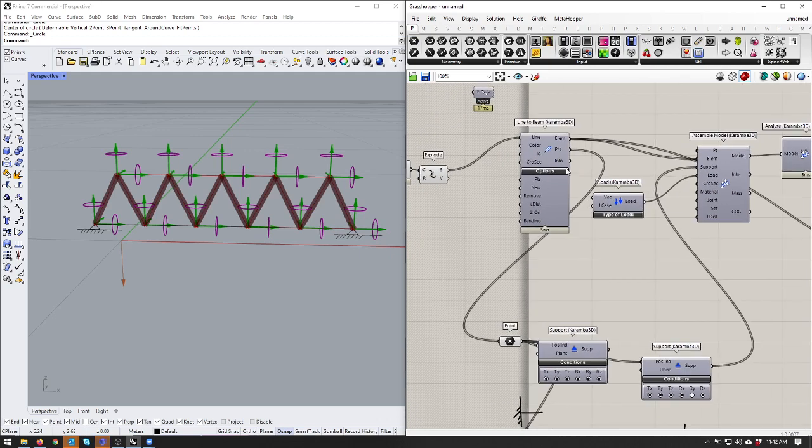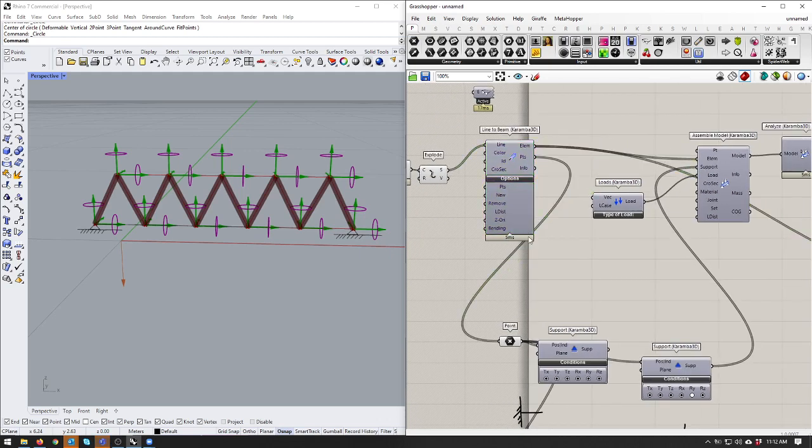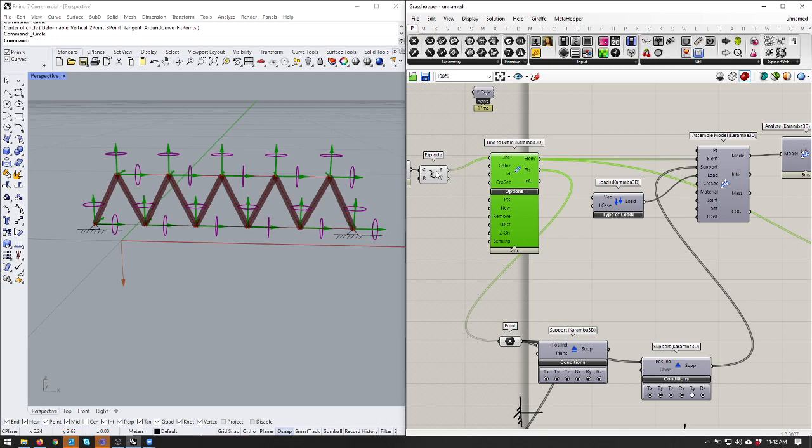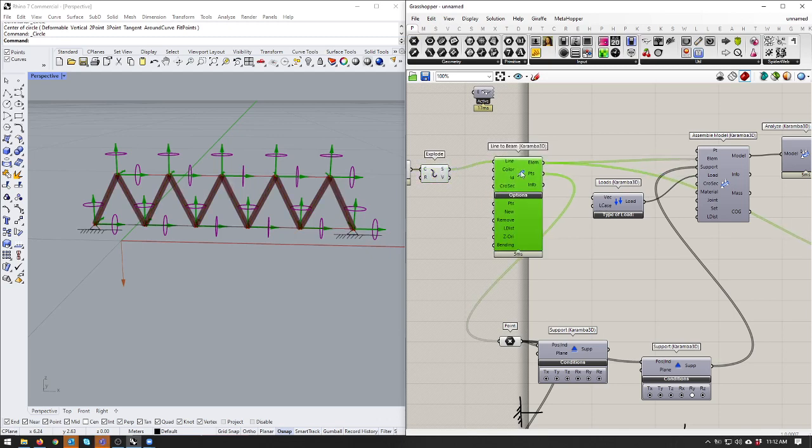Do you remember how I built the supports before? Yep, you built using the line. Yeah, so I took all the lines and chucked them into the line to beam. You use the points of the line, the points to build support. So all of these nodes have now turned into supports. What I've effectively done is I've got a hand of God coming in and holding all the structure up. And this is something that I've seen in so many people's designs coming out of this class,